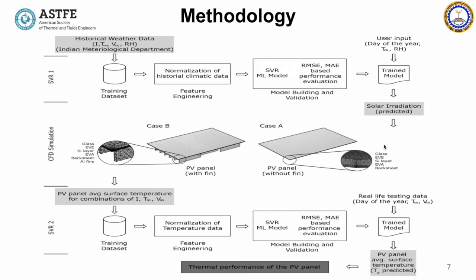Then data was collected to train the second SVR model. The SVR2 model predicts the solar PV panel average temperature. In that, the PV panel average surface temperature was collected from CFD simulations, and this data is trained using SVR, and after that it predicts the panel surface temperature.